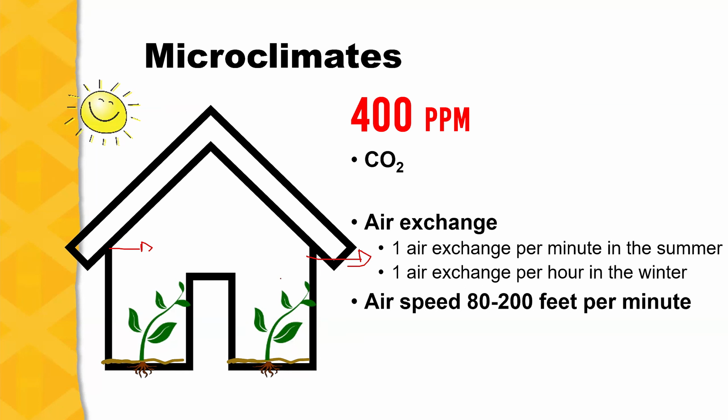Now, some growers, depending on where they are, the location, sometimes it is cheaper to conserve the heat energy because fuel prices might be too expensive where they are. And they may have a CO2 generator or a CO2 tank next to the greenhouse that will inject CO2 into that structure. And they did the economic analysis, and they found for their specific operation, it was cheaper to put in CO2 than to have the additional cost of heating that greenhouse by letting air in.